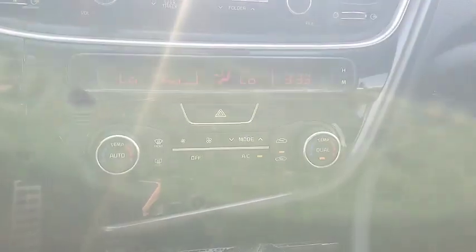Okay, so everything is still good here. I think this car is really pulling, but we're gonna catch it on its own game today. So what I want to do next is, since it often occurs when I shut down the car, that when I put the AC back on, the compressor will not respond. So I'm certain by now that even at this point it is allowing a very reasonable amount of power to go to the compressor, which is around 12.5, 12.6, 12.7.